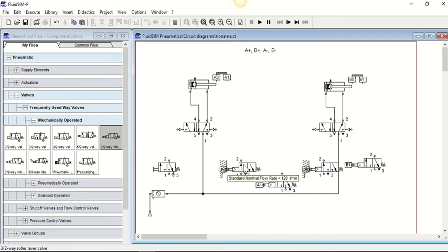So this valve is starting activated, so you can see it switched over as opposed to this one. That's showing it in its starting position because it's starting as activated. We can see that it's allowing air to flow through, but it's still a normally closed valve, like this one here. It's just starting in the activated position. That's what those hatch lines mean.